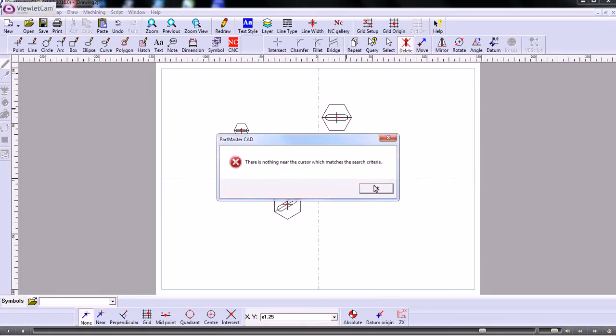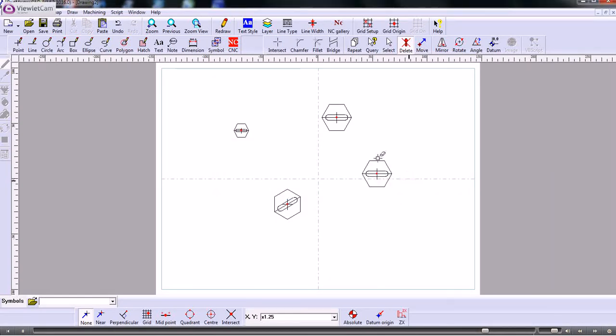So when you put symbols onto a drawing and you want to access them or edit them, you have to go to symbol and then you choose explode, where you can point to the hook point, and then you can access and delete, do whatever you want with it. The other thing that you can do is explode all symbols within there. So now when you do a redraw, you get the point markers showing the endpoints of all those lines.